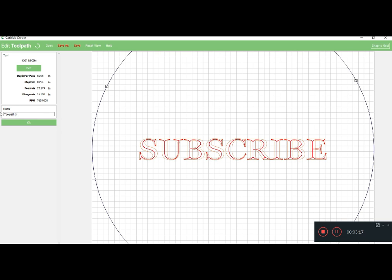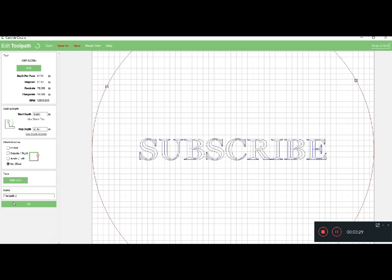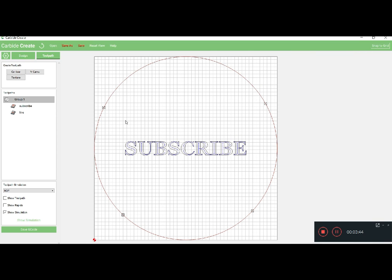Instead of toolpath 3, I'll hit subscribe, hit OK, and then the outside line, I'll just hit edit operation. I'll right click on that, then just click it, and then just put probably line, so I know what is coming up next. So that's the line. There you go. Okay, so we can save that if I wanted to as a G code, and all I'd have to do is send it to the G code, or basically the Carbide Motion.